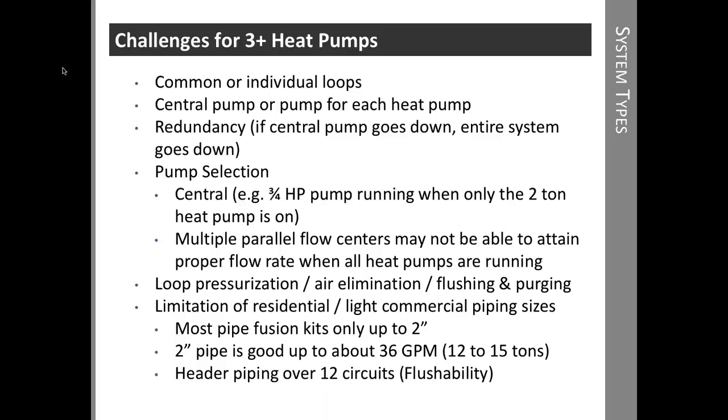So a lot of questions to answer on multiple units, and that's really what we want to concentrate on in this webinar. The first one is common or individual loops, and that'll depend on a lot of things we'll talk about shortly. A central pump or a pump for each heat pump involves some redundancy. If a central pump goes down, the entire system is down. Now, if you have electric heat, you do have emergency heat in the wintertime, but in cooling, there will be no cooling, of course, if our central pump goes down.